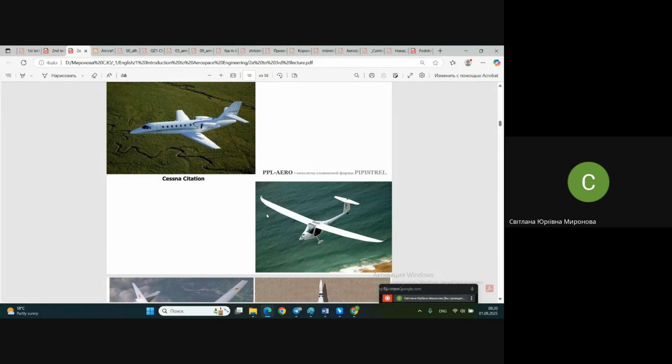Moreover, here we have a straight wing. It's a bit tapered, but straight. And this straight wing means the airplane is purposed for low speeds. And where you see sweepback and a sharpened nose, it's not for beauty, it's for drag minimization at higher speed.